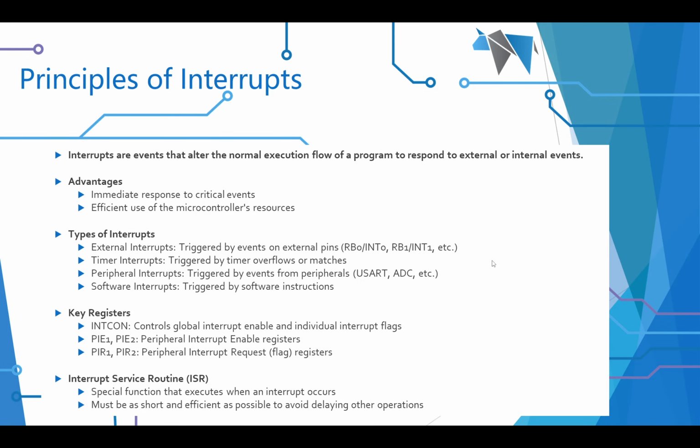So let's look at what these interrupts are all about. Interrupts are things that stop the normal execution of your program. You define an interrupt, and it will stop that normal execution, go and do what you define as being the interrupt handler, and that permits you to respond to external or internal events like a timer. It really has some huge advantages in terms of its responsiveness. It uses the microcontroller extremely effectively.